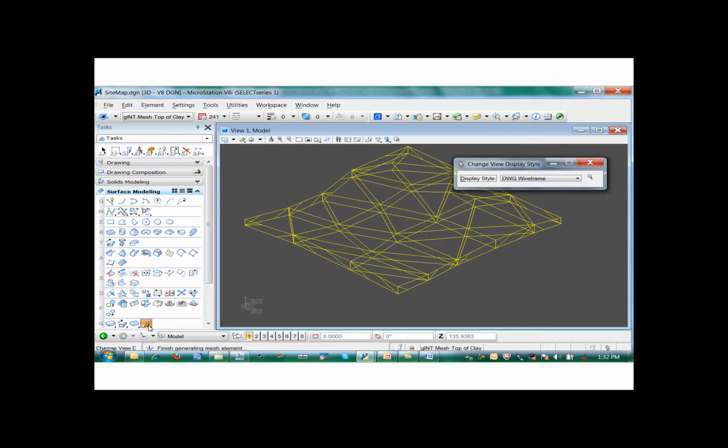I'm going to run this command and the dialog box will show up, and there are two types of solids I can create, smart and primitive. You can refer to help to find out about the differences. I'm going to select smart solid. I also have the option to keep original. This time I won't, and click on it, and again in the drawing area.